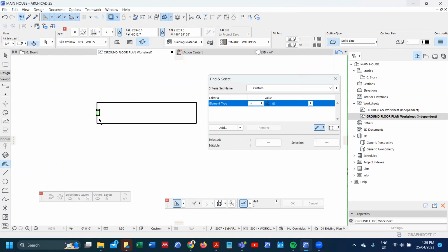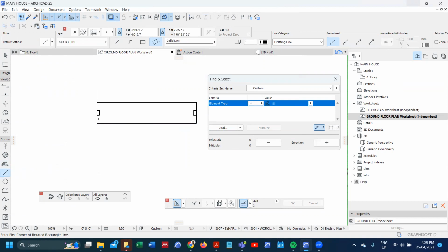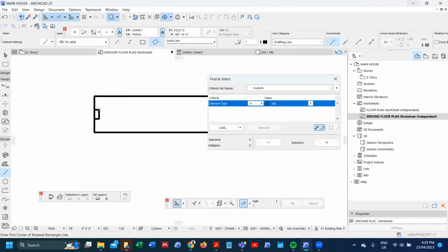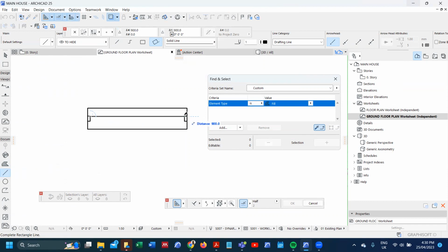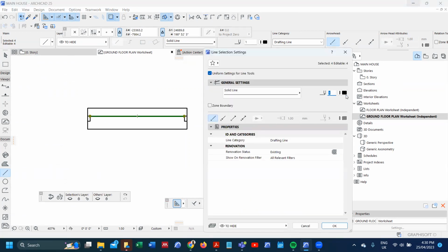Okay, we'll have one on that side and another on this side, okay? We might have extra transform styles, but for now, I will avoid that because of the scale that we are working in, okay? So what I need to show is the glass. Glass will definitely be not more than 5 millimeters, but you'll realize that showing 5 here would be showing it as a double line.